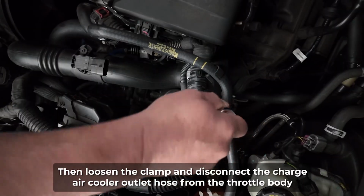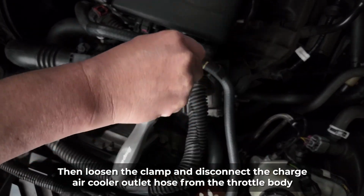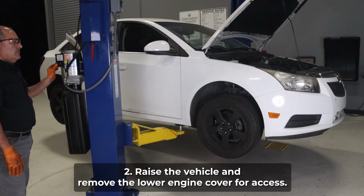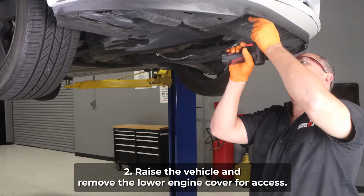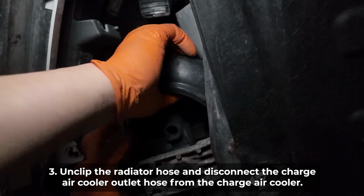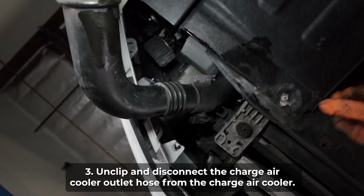Then loosen the clamp and disconnect the charge air cooler outlet hose from the throttle body. Raise the vehicle and remove the lower engine cover for access. Unclip and disconnect the charge air cooler outlet hose from the charge air cooler.